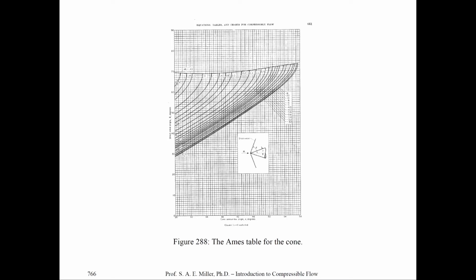This is 1.4. This is 1.5, and it goes all the way out to the asymptotic limit of M equals infinity. You can see there's very little change in high Mach numbers between Mach 20, 30, and infinity way out here. And so, of course, the curves are bounded in the theta-beta-Mach number solutions of the cone. Remember, the theta-beta-Mach number equation is not the same for, say, cones and wedges, and that's why we're getting different graphs. In fact, you can see there's no upper family of solutions for the theta-beta-Mach number equation. There's nothing plotted up there.